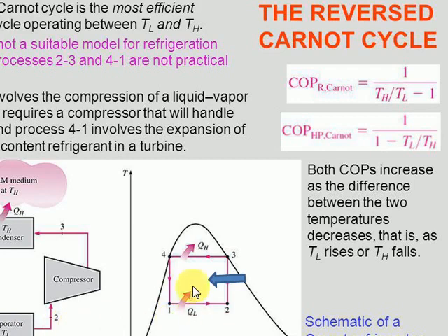to the refrigerant. At state 1, refrigerant is liquid plus vapor. That means less is vapor, more is liquid. And as the heat is added from the cold medium, the balance liquid starts converting into vapor.